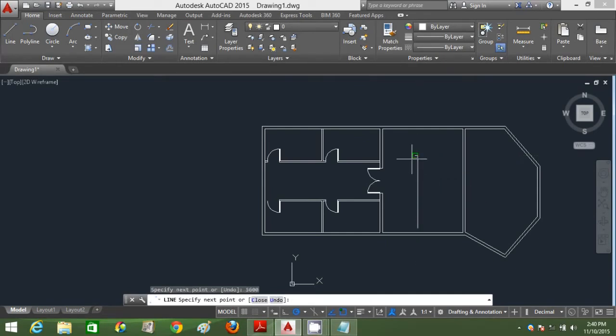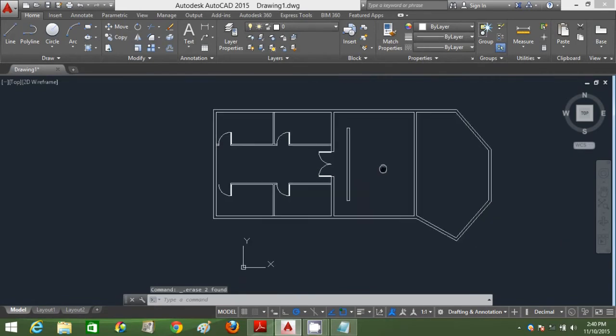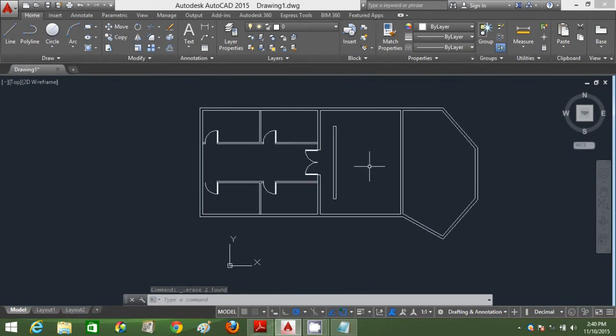Okay, for the reception, using the dimensions stated on the floor plan layout. Alright, so I'm just gonna draw it first, then move it later to centralize it. So I'm just drawing my reference lines first by 1000 mm and move the backdrop wall there. So after that, I can delete all the reference lines. Alright, I've created the backdrop wall.